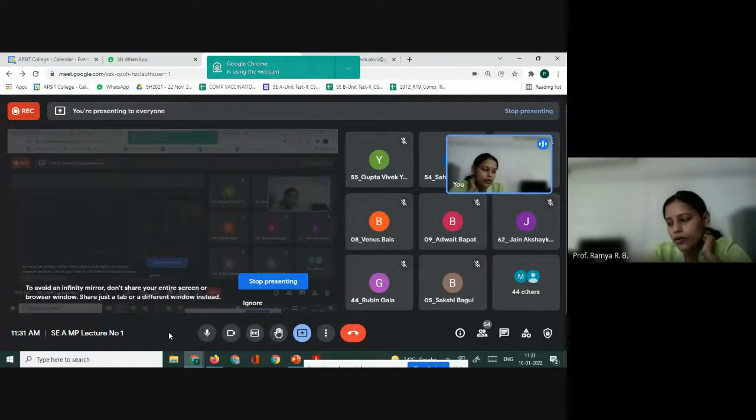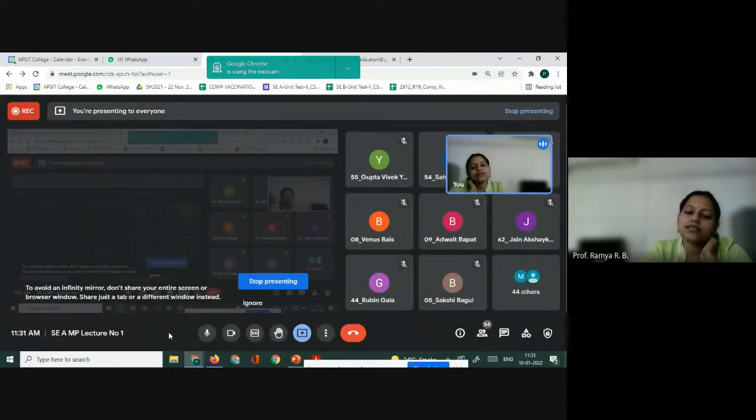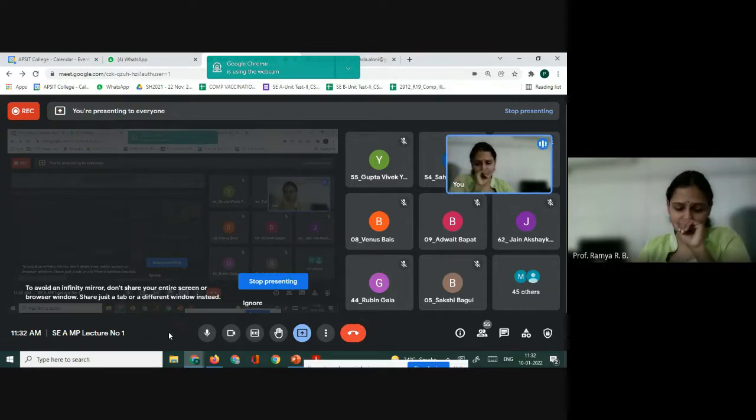So 8086 is a basic microprocessor. It's a 16-bit microprocessor with an adequate instruction set, and it does have some additional features when you compare it with 8085. So we are learning the subject using 8086, and when we start learning the subject, you'll be able to identify what features are there in 8086 and which are not there in 8085. So we just now answered three questions.